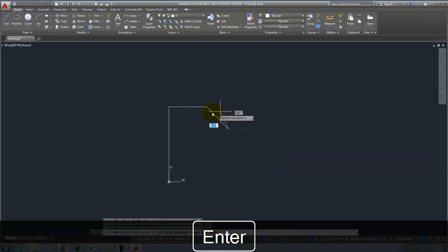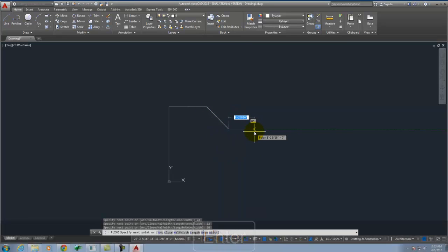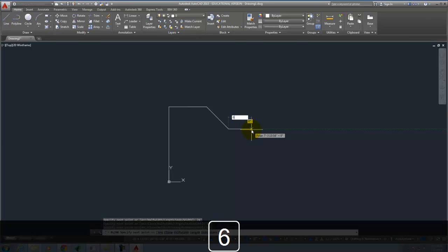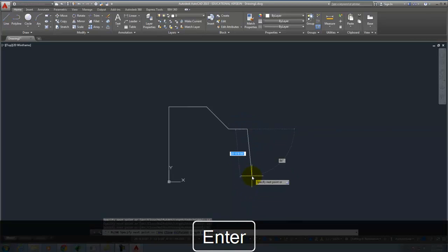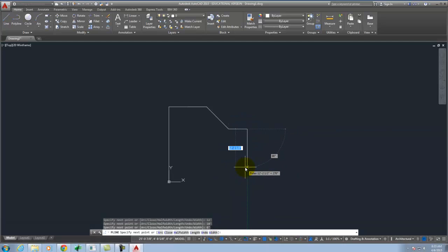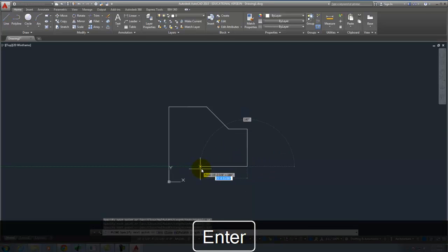And then it would go 10 feet at that 45 degree line. Does that kind of make sense? Okay? So the key is that when you're drawing using this dynamic input, it ends up being relatively fast. So I could say 6 feet, and then we could go, I don't know, 12 feet. And 6 feet. And you can kind of just follow yourself around here. Let's go another 6 feet there.